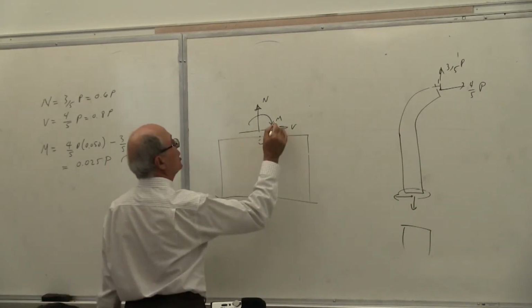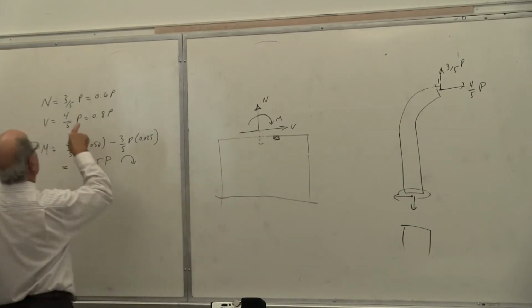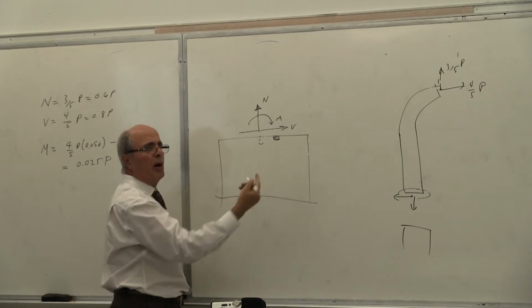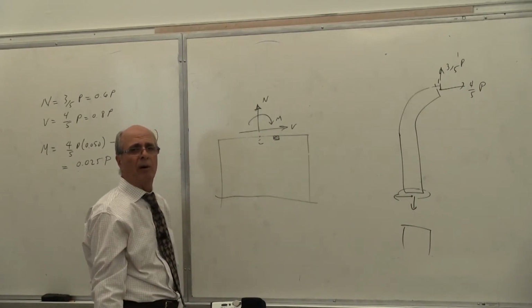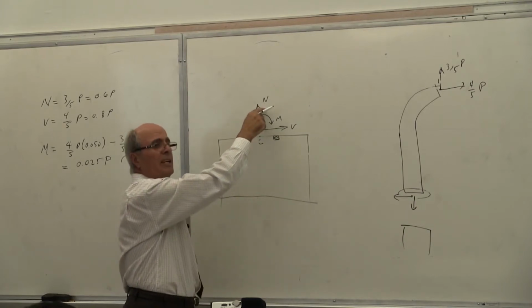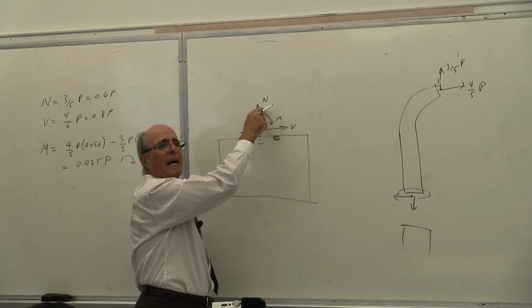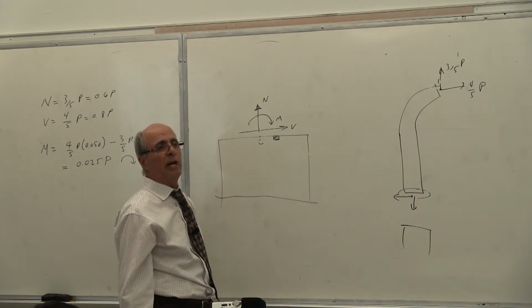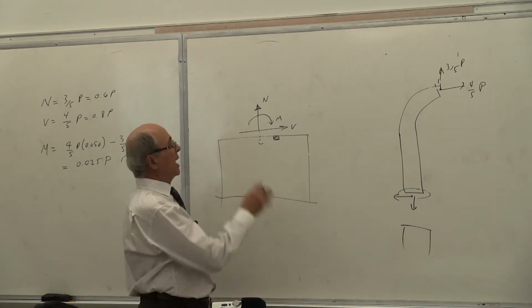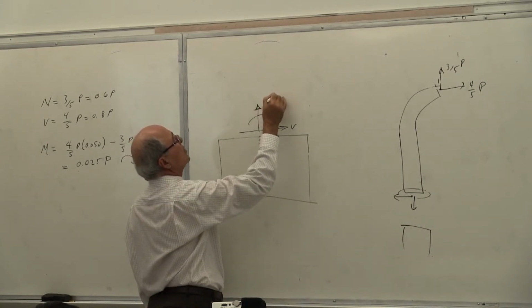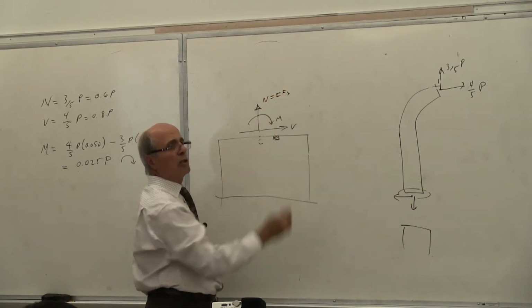So you have this much M. You have that much shear force. You should not show that as Fx, Fy. What are you talking about, Fx, Fy? They call this Fx. Some of you call this Fy. That is a normal force acting on this section. Yes or no? Which is sigma actually. Sigma equal to N over A. That's where the understanding comes from. When you start writing this force as Fy, I don't know even what you are talking about.